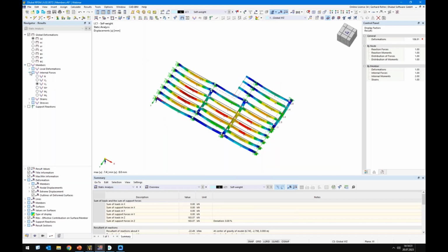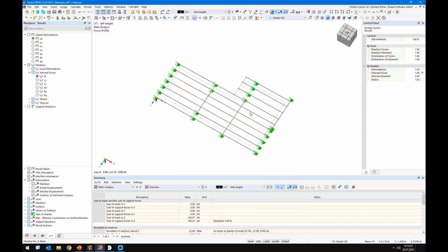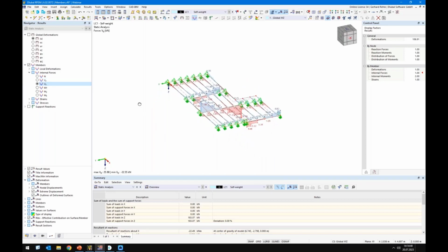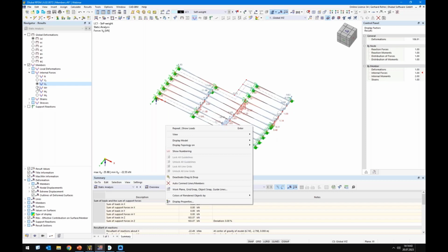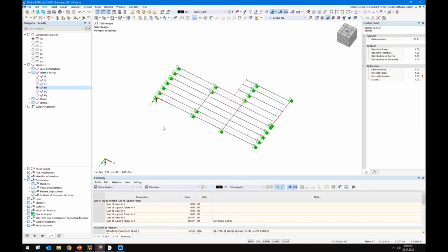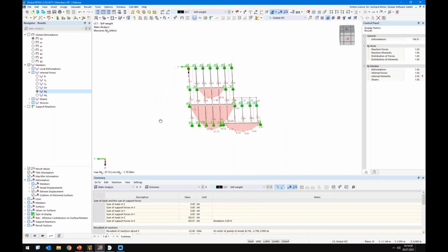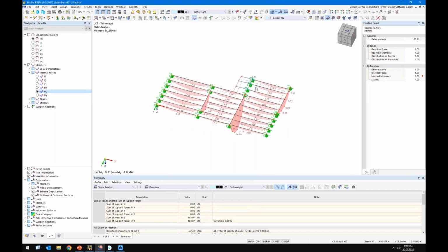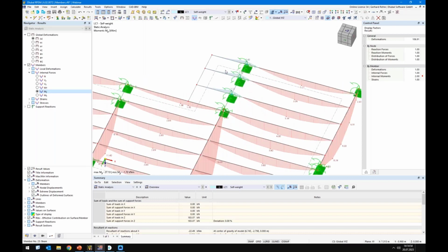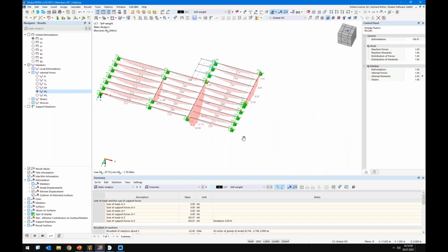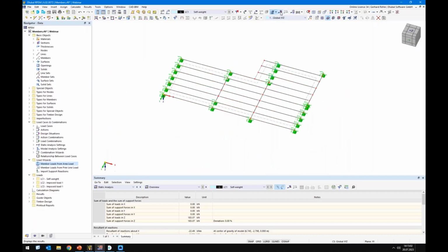Let's switch over to internal forces. So we should have no normal forces inside, no shear forces in Y direction, only in Z direction. That makes sense. And no torsional moments, that's also good. Bending moments look like for every one-span beam, that's okay. Here we have our hogging moment, which is also fine on this cantilever. Okay, looks good so far, and now we can start to think about the design.